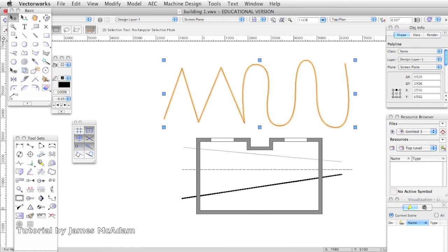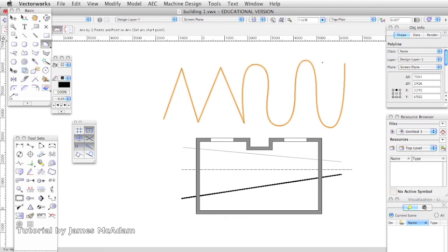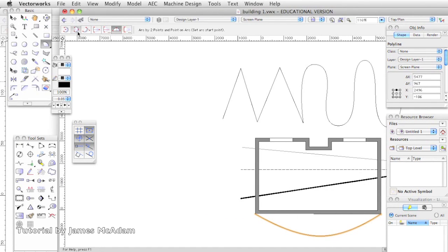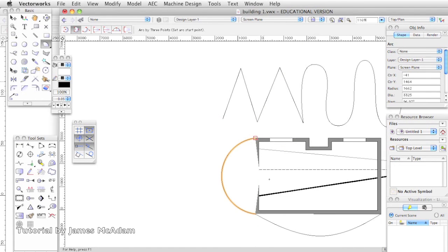So the other types of curves you can use are arcs, and you have a bit more control in terms of input for these ones. So this is just a usual polyline drawing an arc. It won't be symmetrical. So if I use this tool, which is an arc, and we get another set of ways of controlling it, I'm going to use this second one in and click one point, click the top of the arc, and again the last point. So you can see how it's making an arc between 2 points and a height. And get rid of the fill.